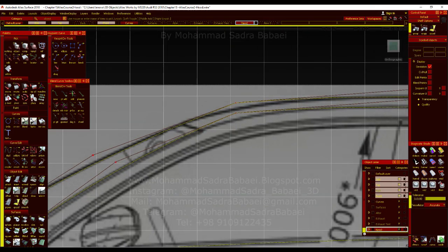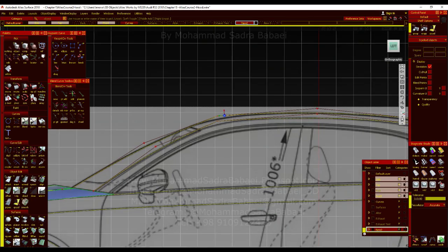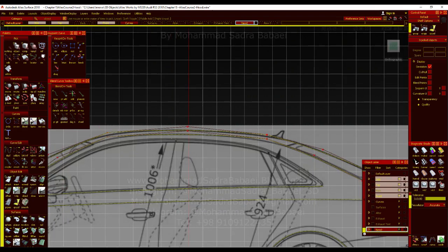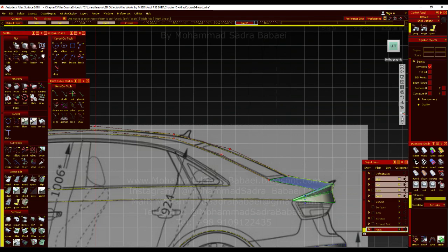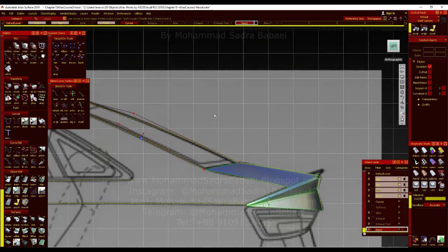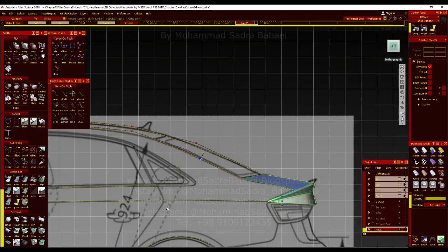What I can do here, for example, I can use freeform blend to connect these two surfaces, these two curves, and after that I can use symmetry align, for example, but take care of the CVs of the surface before using the symmetry align tool. And after that you can have sharp surfaces and add a fillet between your surfaces.